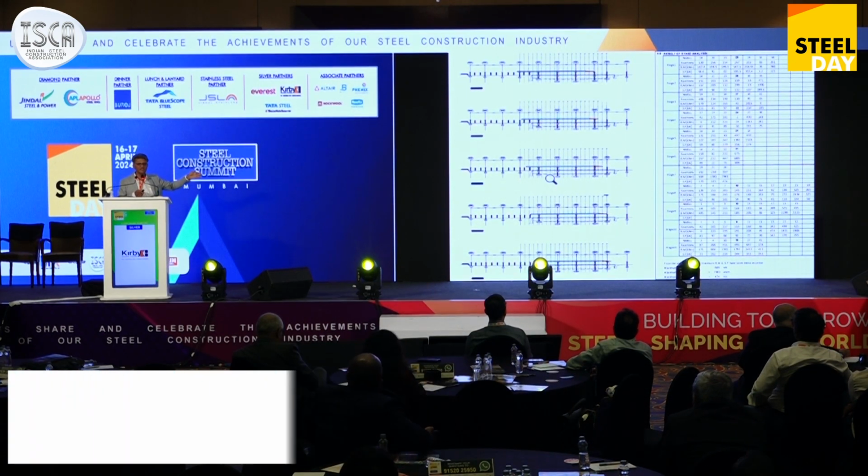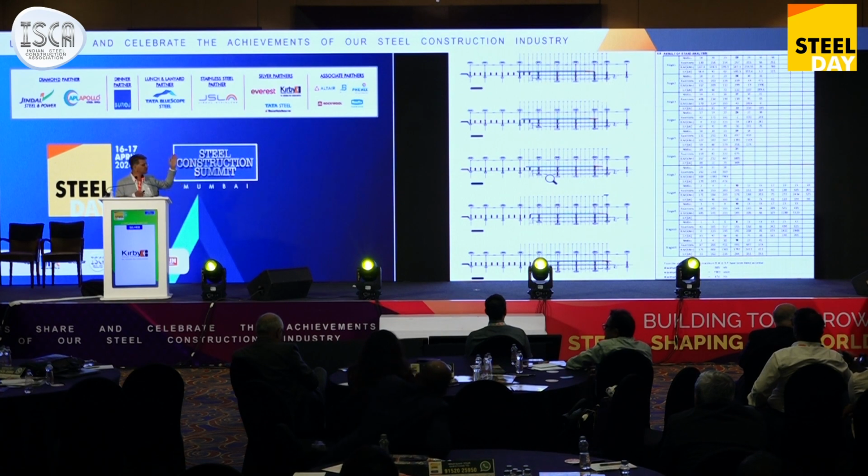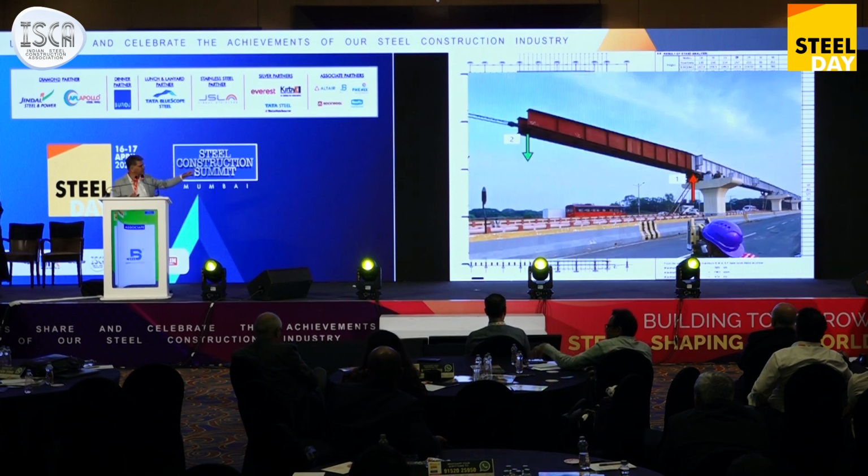We analyzed the entire structure for every 1 meter, because for every 1 meter the bending moment and shear force diagram will change. Accordingly, the front support gets the maximum reaction and the front tip gets the maximum deflection. For every 1 meter we analyzed in the STAAD model, and every stage has been confirmed.